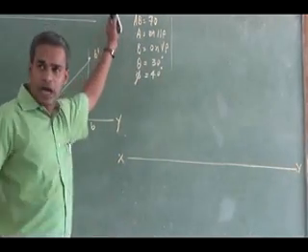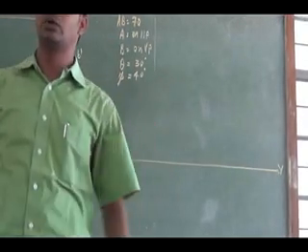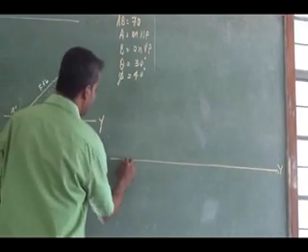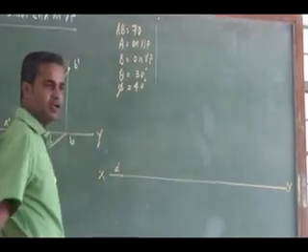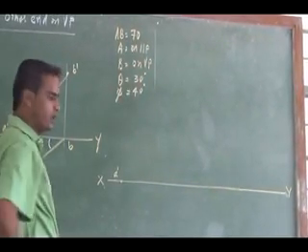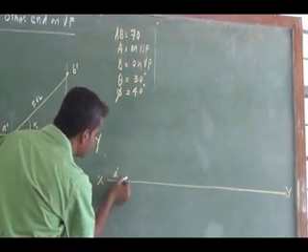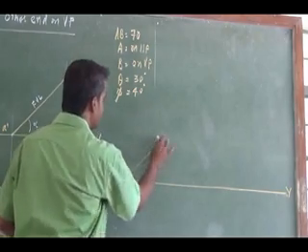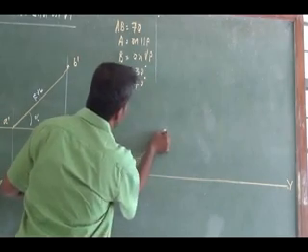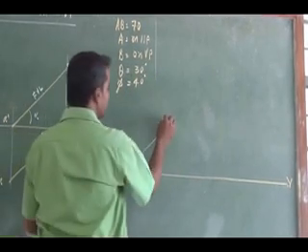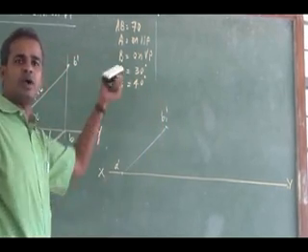You see here, first, as the first assumption, the line is inclined only to HP and parallel to VP, right? Similar to that, I can have a point in the first step. That is my first A dash. I can mark it. I know A dash is on HP, right? Then the true inclination is 30, true length is 70. Using that 30 and 70, I can draw a line. So this is going to be my 70. Right. So this will give me B1 dash, an arbitrary location.